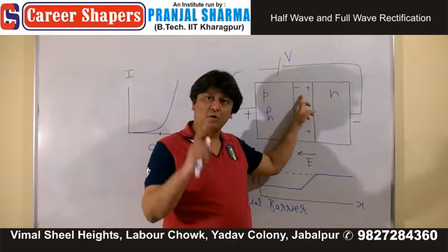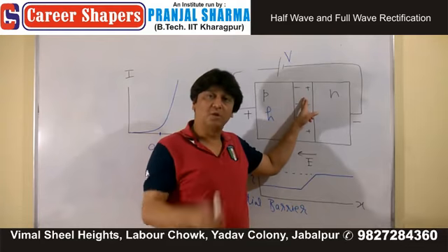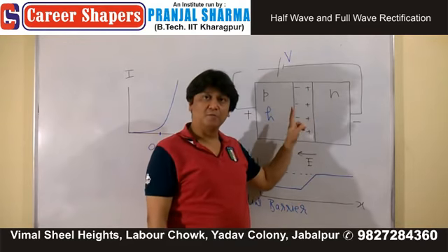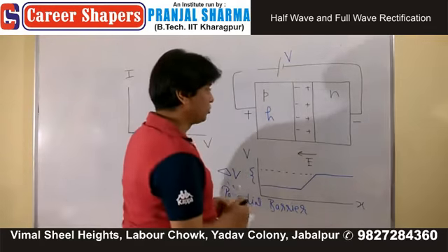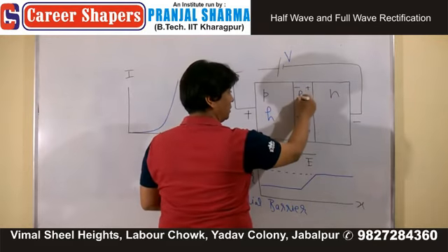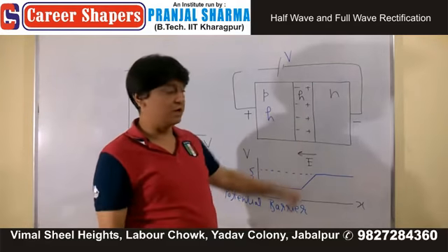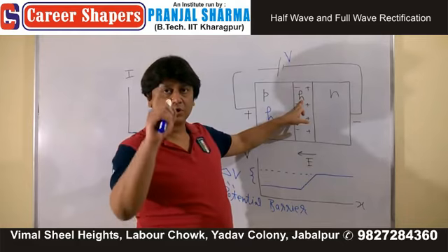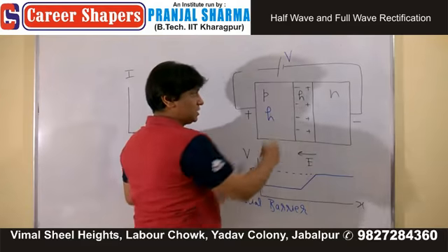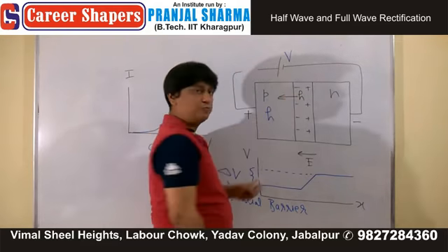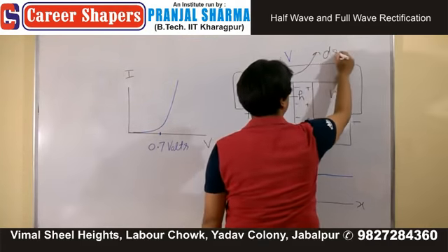Those holes and electrons which you create in the depletion layer because of thermal collisions, they move because of this electric field. Suppose you create a hole in this region, in the depletion layer, then this hole is going to move in this direction because of the electric field. This hole, when it moves, it gives us drift current.